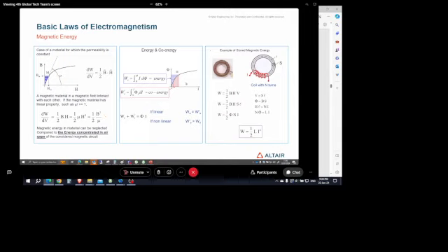Yeah, you will hear about virtual work method that use co-energy. Co-energy has no physical meaning, but it's like the pendant, I don't know how to say it in English, of the magnetic energy, and it uses this co-energy concept to compute magnetic forces.